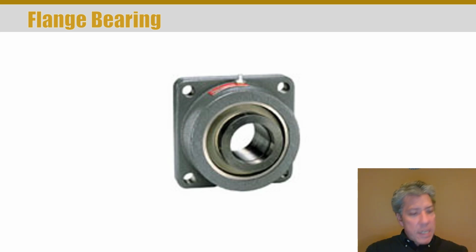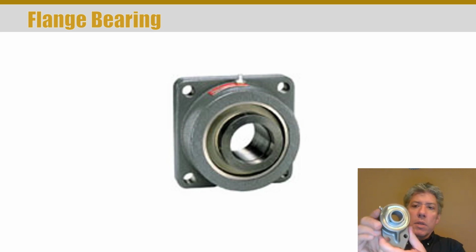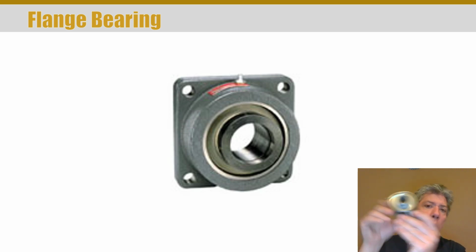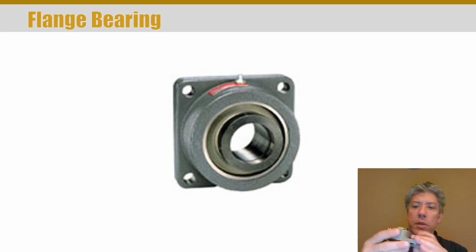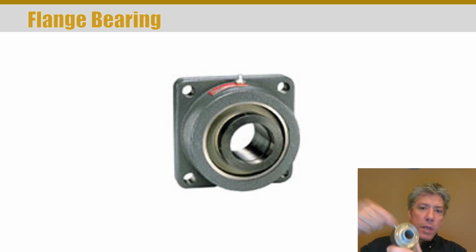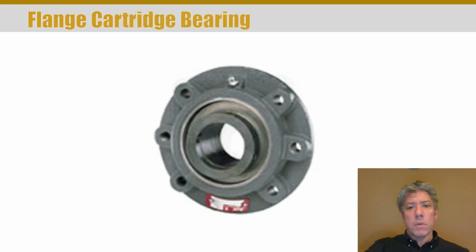So there's many different options in these. There's another type that I don't even have in the presentation. It's this type, which is interesting. You bolt it on one side rather than on both sides of the bearing. But all these are essentially the same idea. You've got the insert, you've got a grease fitting for putting grease into the rolling elements, and you've got options in the insert as well, which is nice.